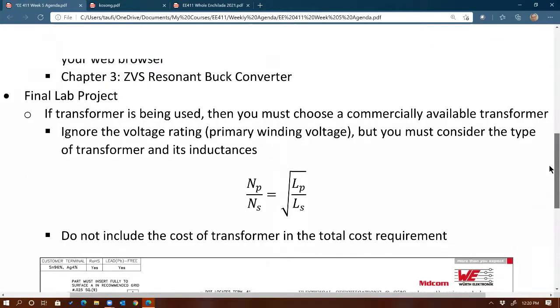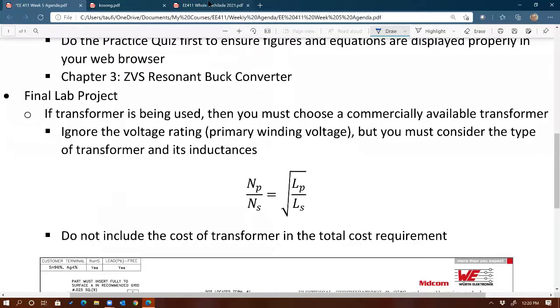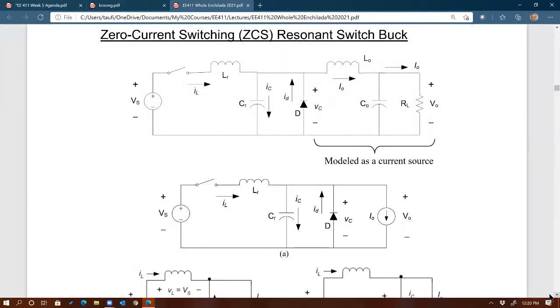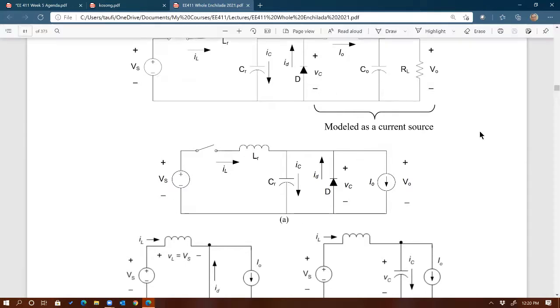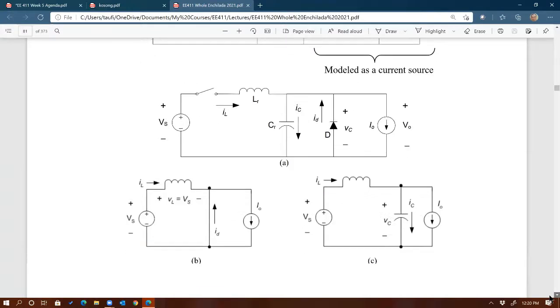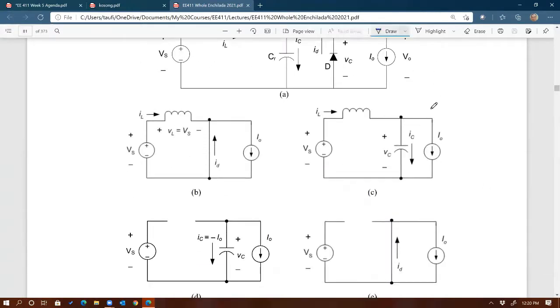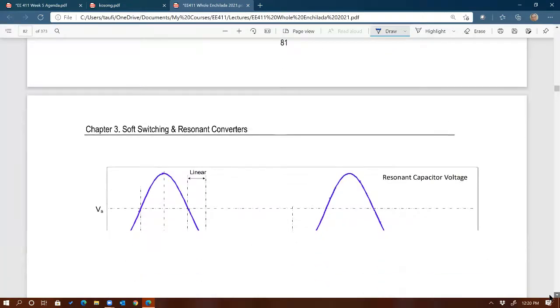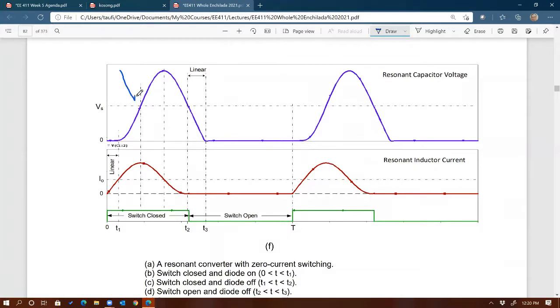Okay. Any other questions? No? Okay. Now let's finish our ZCS right there. So we already analyzed the circuit, mostly using KVL, KCL. That's all we needed for this circuit. And then we found out that this is a buck converter from the equation that we derived last week. And then we have the 4 states. One of the states is resonant, that's the resonant state right there, where the waveforms on the inductor and capacitor are sine waves, starting from that point.